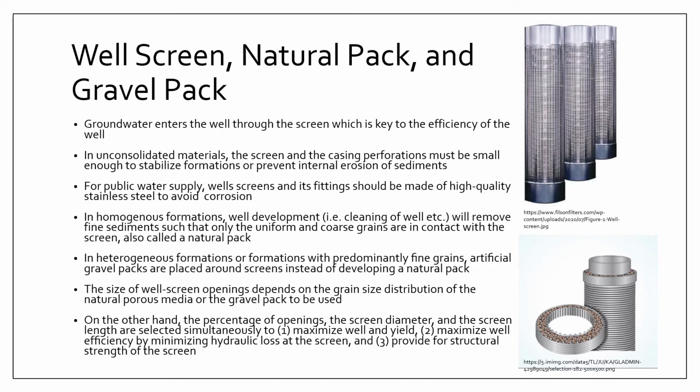Right? So well development will typically involve pumping the well to remove the fine sediments until we thoroughly clean the area around the screened length, right? And the only material that will be left behind are your uniformly sized and coarse grains that have good permeability, right?